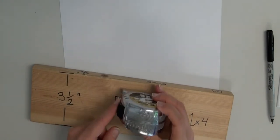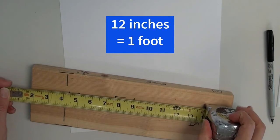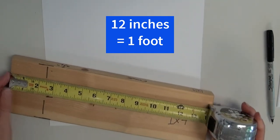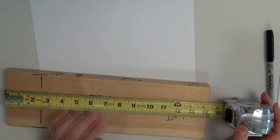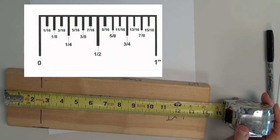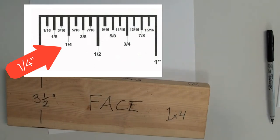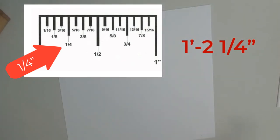For those of you who don't have experience using a tape measure, I just want to really quickly go through how this works. So this measures in inches and feet, and you hook the little end onto the end of what you're measuring, and you can see there's 12 inches equals 1 foot, 13, 14, and then it looks like that's 1/4 inch. So that would be 1 foot, 2¼ inches.